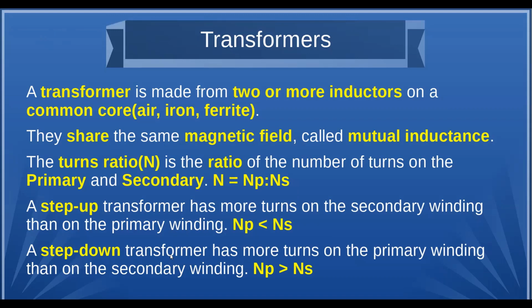And a step down is just the opposite. I'm going to have a lower voltage out, which is what you would have normally seen in older electronic equipment where you got 120 volt AC coming in, and then you want to get, say, 12 volts out. So you step it down to around 12 volts and then regulate it to get 12 volt DC. And in that case, you're going to have more current on the secondary because you got a lower voltage.